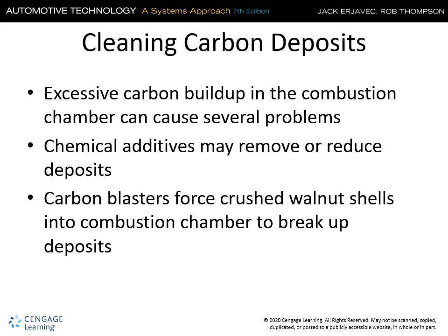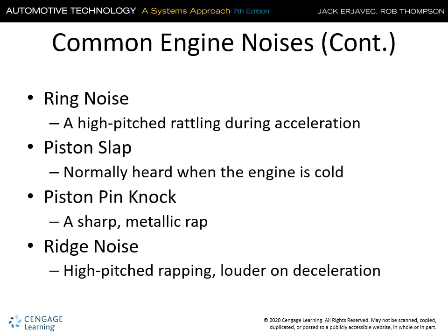Excessive carbon buildup causes thermal problems. The heat isn't able to transfer into the coolant, and there are methods of using additives like Seafoam and walnut shells to break up deposits if you're doing an overhaul.